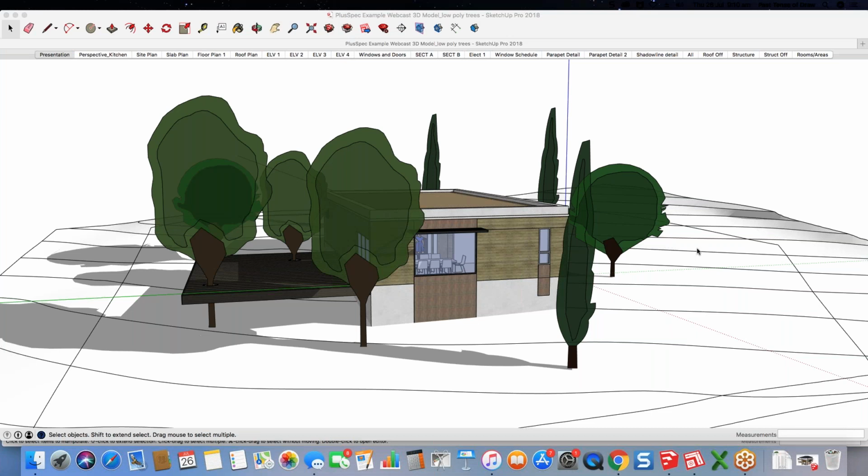RL means real level. That's a question that's come through already. There's a lot of different terminology, and it's fairly common around the world. So what is the real level? Typically, it's based off a datum point. When you're working with a site, such as what you're seeing on screen, when you're creating your contours or your site map, often that will have a datum level where the site surveyor has gone out and calculated the elevation heights.